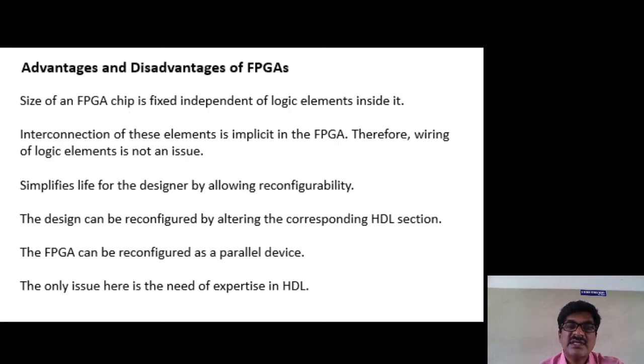What are the advantages and disadvantages of this FPGA compared to other ways of realization like ASIC realization, microcontroller realization, and discrete component realization? The FPGA has a fixed size; it doesn't depend on the logic circuit which you are going to implement. Internally it has interconnecting wires and programmable switches, so there are no issues with interconnections.